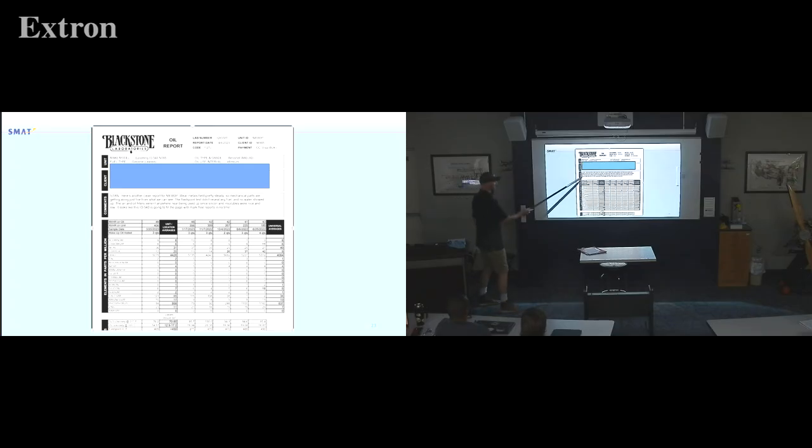I'm gonna come up to this section and say, Stan, here's another clean report. Wear metals held pretty steady, so mechanical parts are getting along just fine from what we can see. The flashpoint test didn't reveal any fuel and no water showed up. The air and oil filters weren't anywhere near being used up, since silicon and insolubles were nice and low, basically saying it's not passing through your system. It looks like this IO-540 is going to fill the page with mark-free reports in no time.